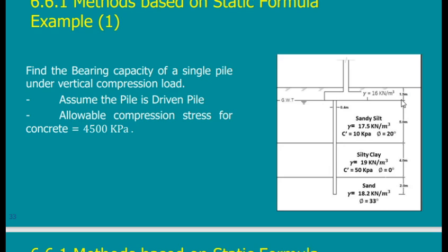6.5. No, not 6.5 over 2, because you calculate the middle of the layer first. This is the middle of the layer. So it is 5 divided by 2. But what is the depth of this middle of the layer? It is the top of the layer plus the upper layer. It's just a load on the pile. It has nothing to do with the pile itself, because this 1.5 meter is a load on top of the pile, but it is not the middle of the layer.